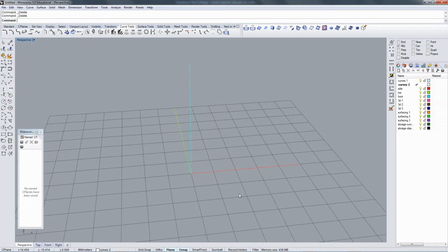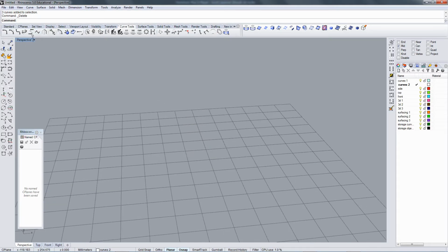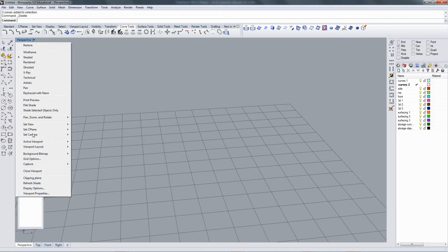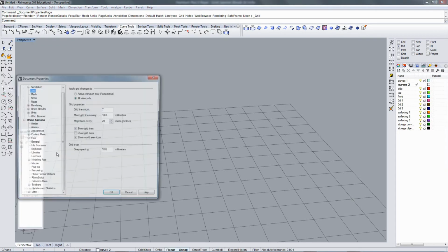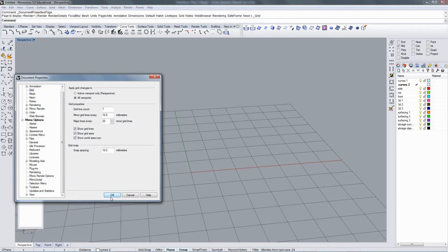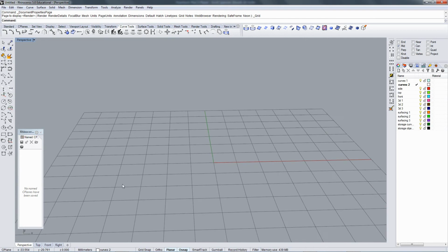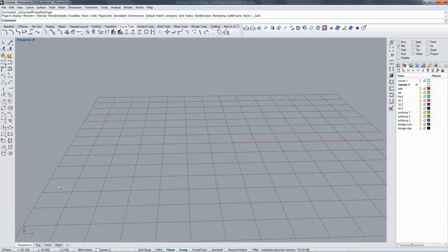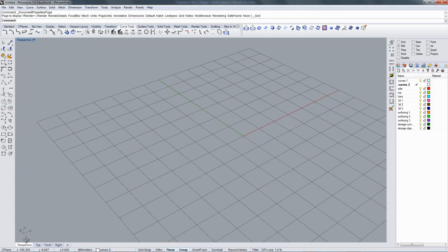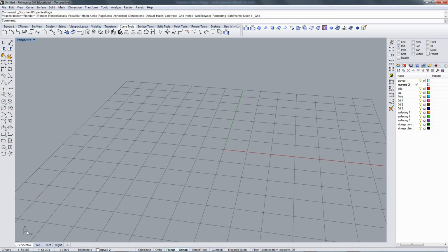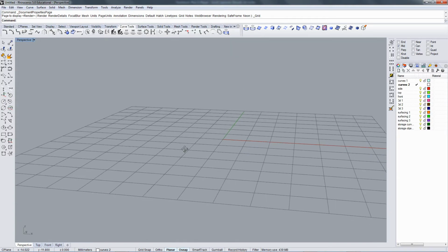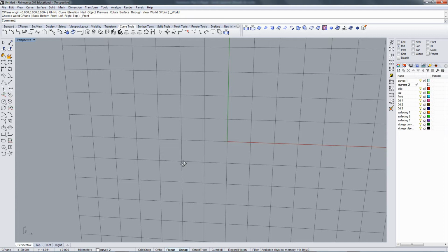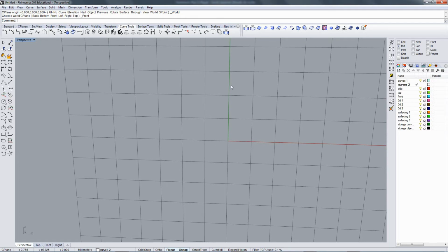The next question that will come up is why. I'm going to turn back on the grid axis again. I'm sure you'll get that from here. Okay. By the way, even when it's off, over here in the corner, there's always a little grid axis icon that shows you global coordinates, X, Y, and Z. And you can see it matches. Red is X, green is Y, Z is blue but invisible. If I go to the front C-plane, X is red. This is showing as Y, which is green, which is correct for local coordinates. But on the global here, you can see it actually would be blue or Z. Okay.